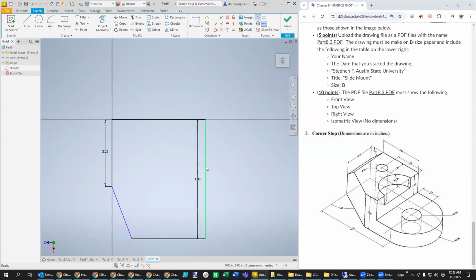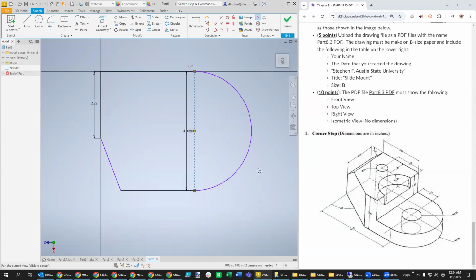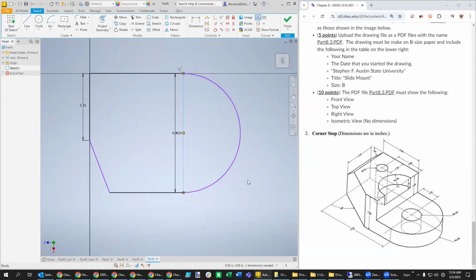That's looking good. We want to make this right here a hidden line. And then the center point arc is going to be at the middle of this, but not hidden. From there, start here, go all the way over there. Is it fully defined yet? Not quite, because we have to get a couple of these other dimensions in place, and that would be this angle.